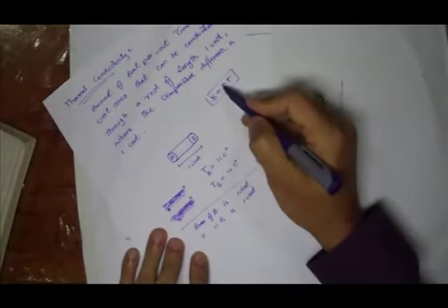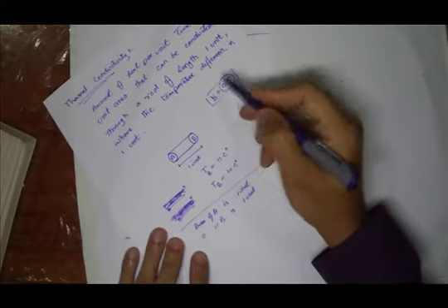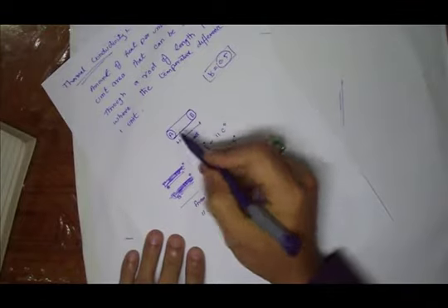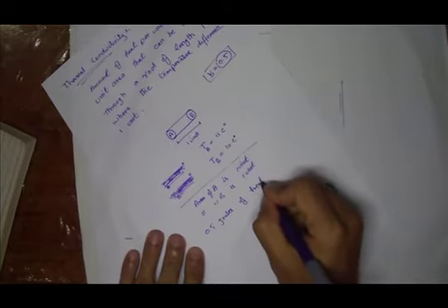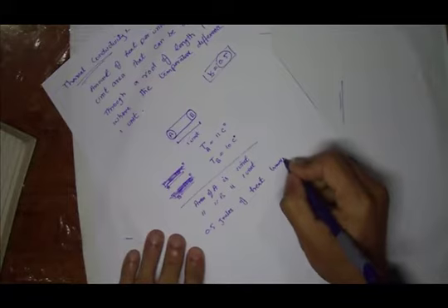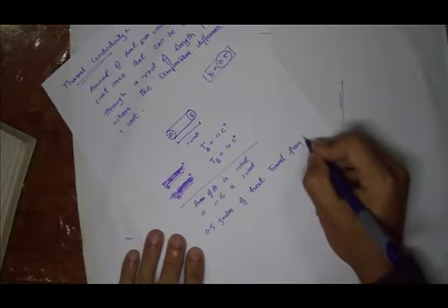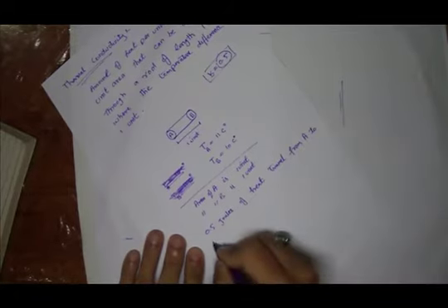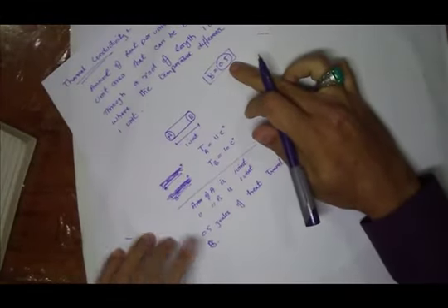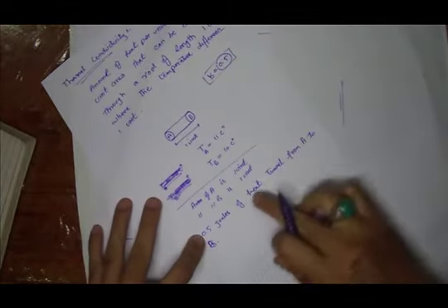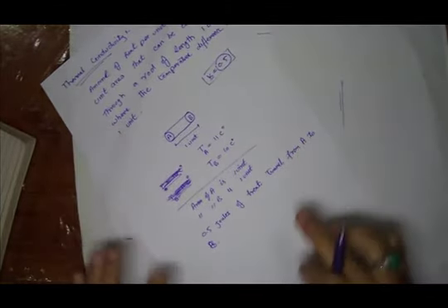In this setting, if the thermal conductivity K is equal to 0.5, it means that after 1 unit of time, meaning after 1 second, 0.5 joules of heat travel from the surface A to the surface B. If the thermal conductivity is 0.7, it means 0.7 joules of heat travel from this point to this point.